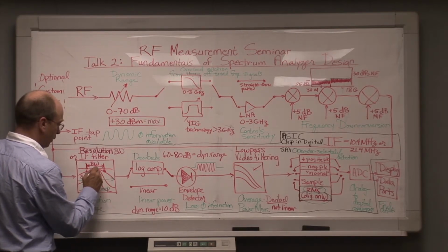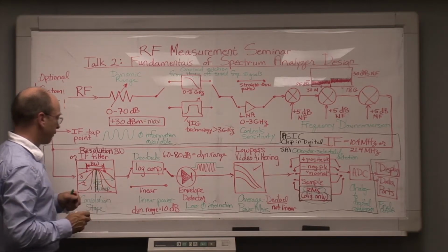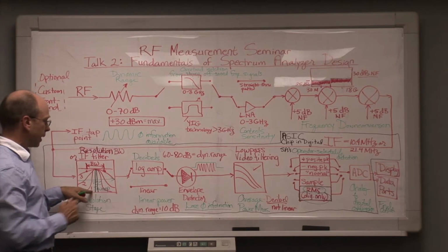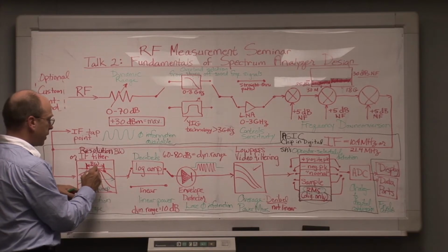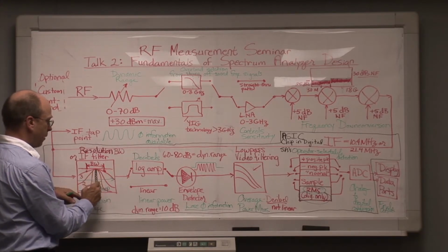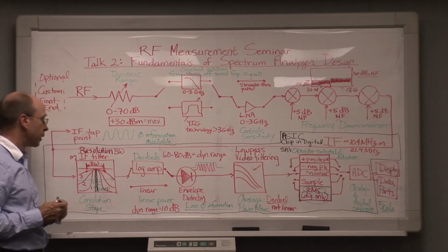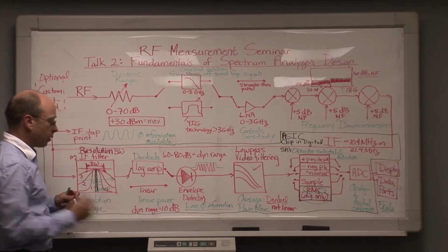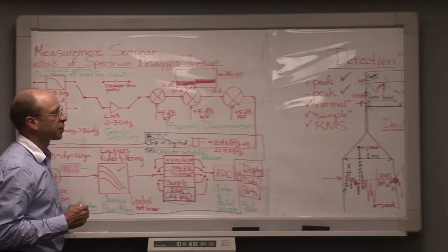If this filter shape were to go to 0 width, like so, then f of omega convolved with g of omega would in fact look like the input function, but the amount of power that we would be able to get through this would be in effect 0 power, and we would not be able to measure any power through the filter.